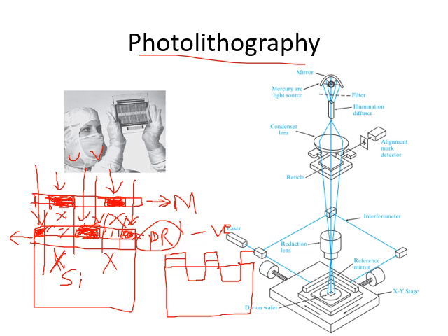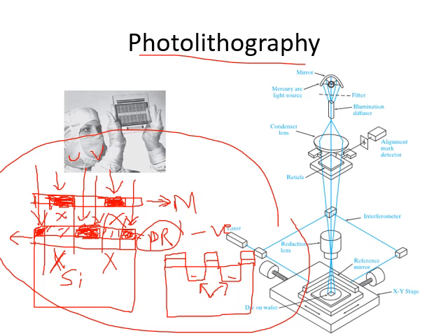Again it will have photoresist and silicon dioxide, and one more window will be created. Again photoresist and silicon dioxide. This part and this part can be etched away. I have shown the diagram after etching, meaning this window is created. Why is this window created? So that ion implantation can be done here. This entire process is called photolithography. Are you following?